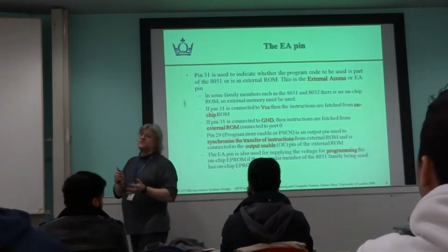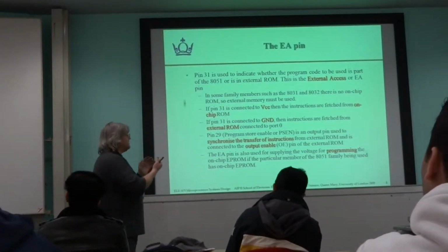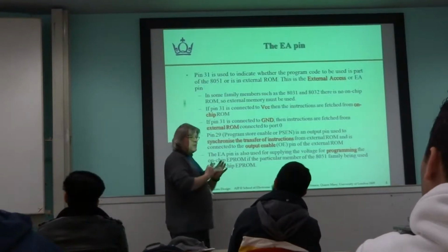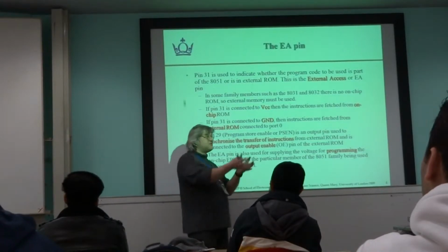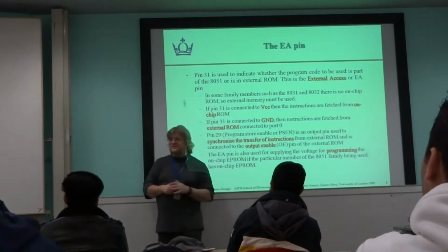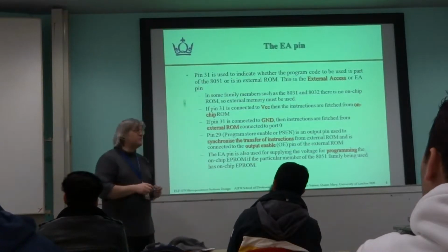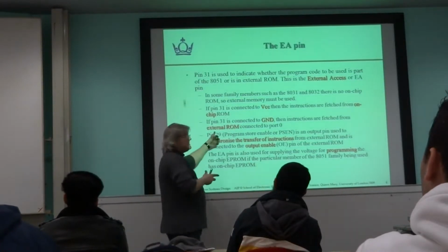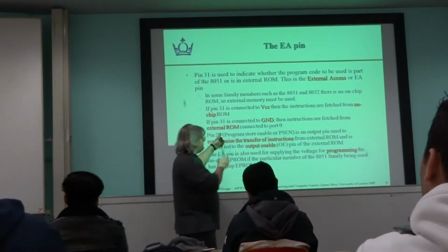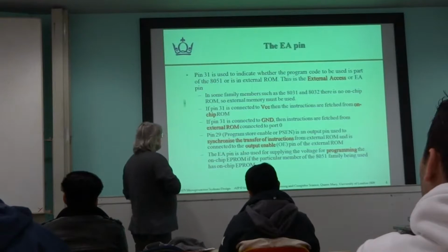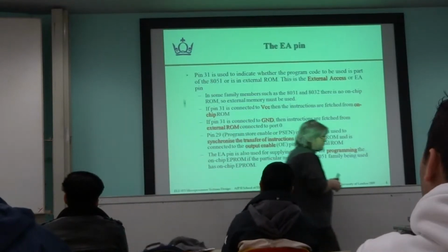Because you've seen as soon as we start to use external data memory, external code memory, we start to lose a lot of our pins on the device. And as a controller, we want to have lots of pins to control heaters, lights, do all those fun things. So preferably, you would buy a device that has sufficient data memory and code memory internally. Okay, so done that pin.